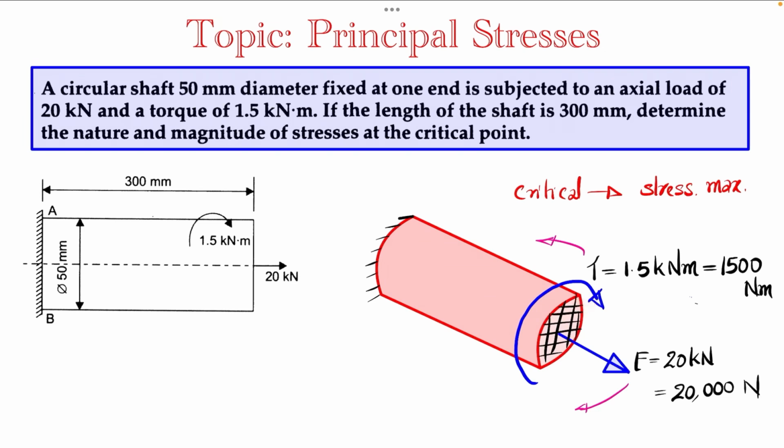So you can take any element. And if you take the torsion loading, our circular cross section is this one, and the torque is applied like this, and we have already obtained the torsional shear corresponding to the maximum. Here I am explaining T by J into R. So this tau will become maximum when R is maximum, and it occurs at this point.